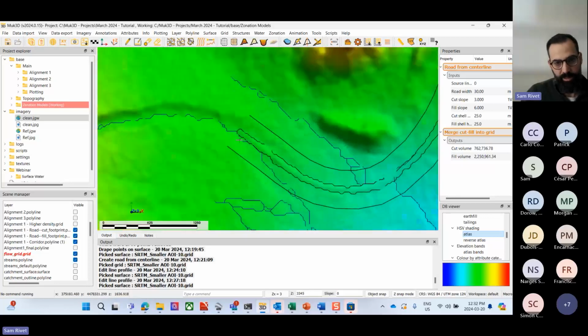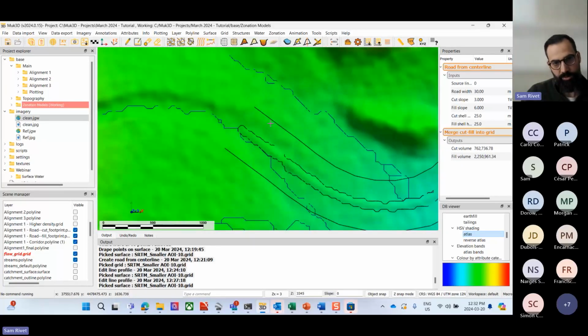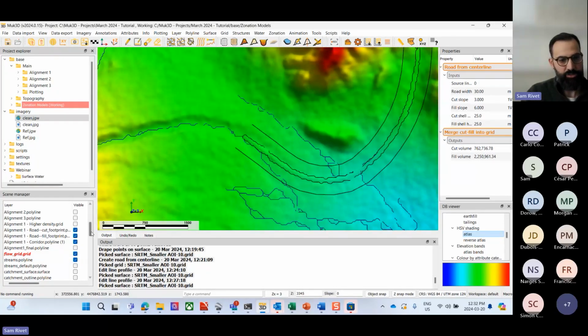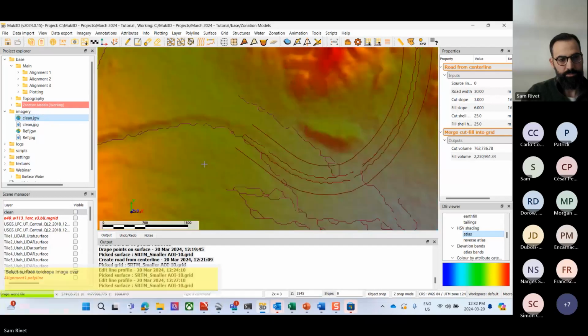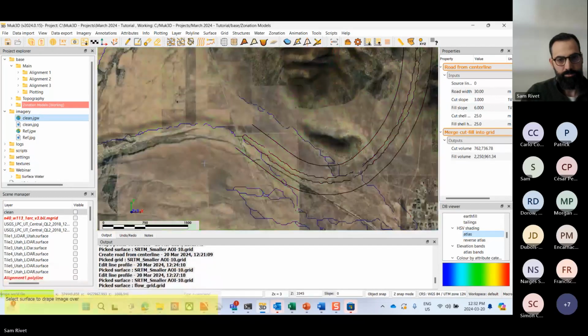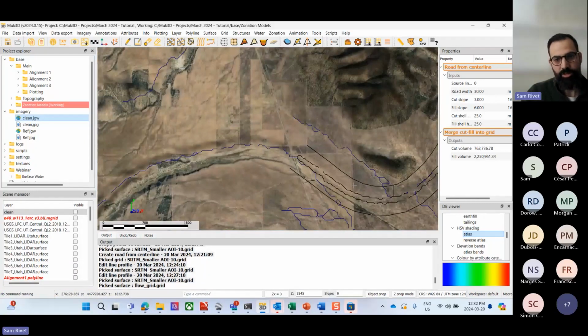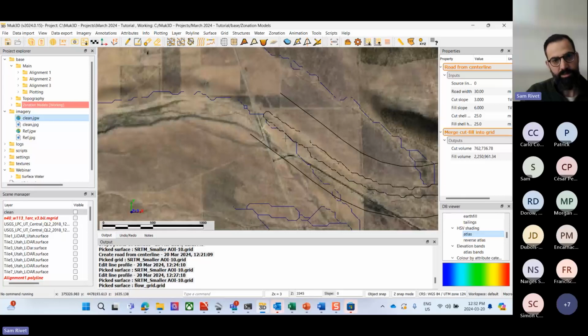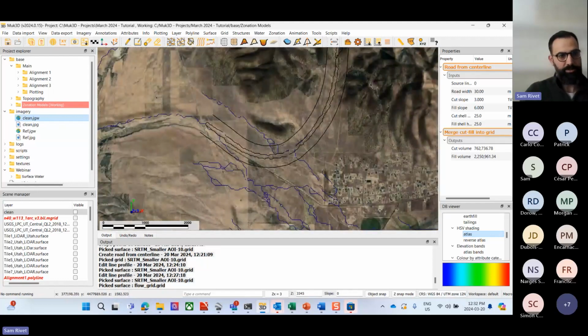Okay, now I'm going to come here, and I have more streams coming into my right-of-way. It's contacting the footprint of my road. However, if I take a look at the imagery here, there is this existing ditch structure. I'm going to assume that the stream here is going to circumvent the road and enter into this stream. There's pre-existing infrastructure here to take care of this. So, okay, I'm not going to worry about that one either.